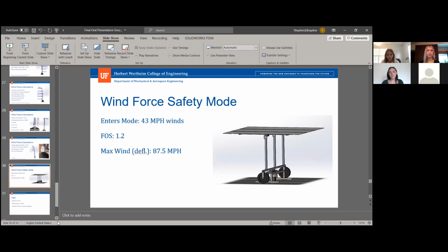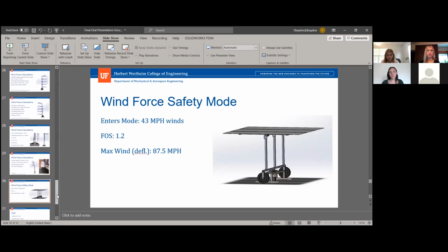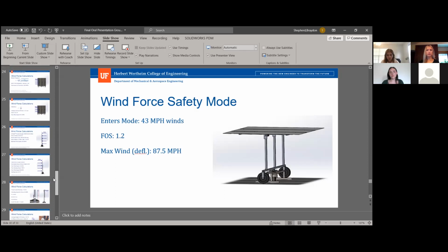Yeah, I'm not so concerned about it in this orientation. I'm concerned about it when it's a 40-mile-an-hour wind and it's gusting to potentially higher than that, depending on how you figure out how this is going to work. But in a 40-mile-an-hour wind, I wouldn't want to put 40 miles an hour on a 1 meter surface that is basically free to rotate about those axles. That's a pretty significant concern. So there's that. While we're on this slide, you've got a factor of safety of 1.2. Is that acceptable to your customer? Because that is very sporty, as we say in the business.